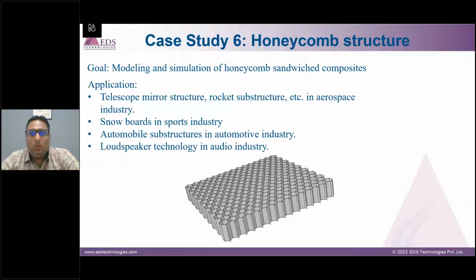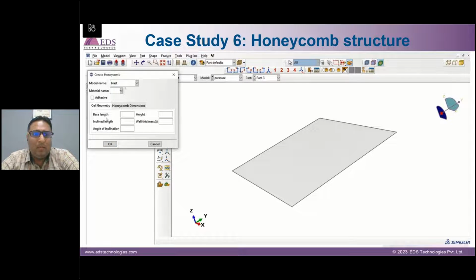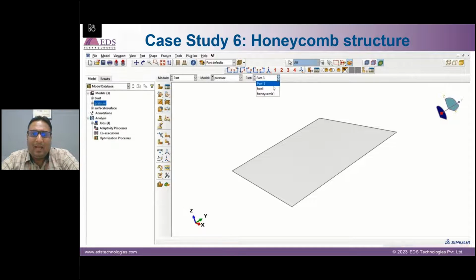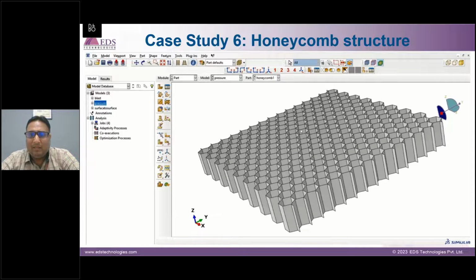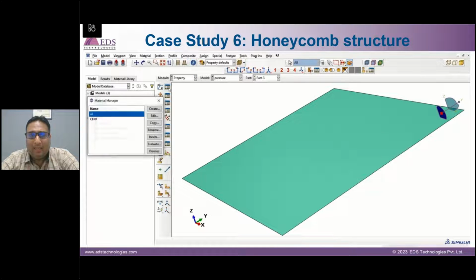Normally in the module, we have to make this structure while doing the modeling in some of the software such as CATIA or SolidWorks. But in the particular module in Abaqus itself, we have a plugin where we can basically, suppose these two parts we have created, we have a plugin known as Create Honeycomb, and here we can select our lengths and cell sizes, cell width, length, everything, and your honeycomb structure is ready. So we need not make anything extra while doing the modeling.